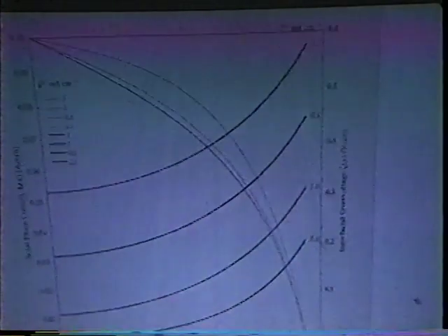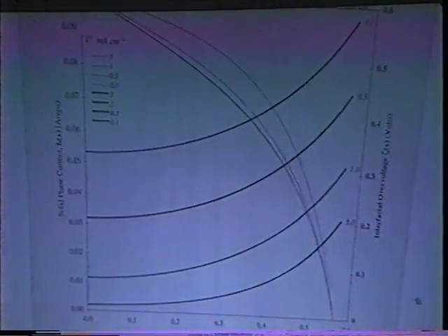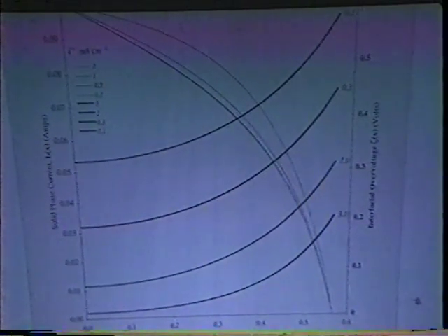We use a rather simple form, the Butler-Volmer equation, where the unknown is the exchange current density, this pre-exponential term, and we don't really know this. So what I've done is solve this system for a number of reasonable values for the exchange current, a parameter which determines how fast the electrochemical process is occurring, in this case the discharge of hydrogen onto the surface of the spheres. So we look at this, we get a solution.